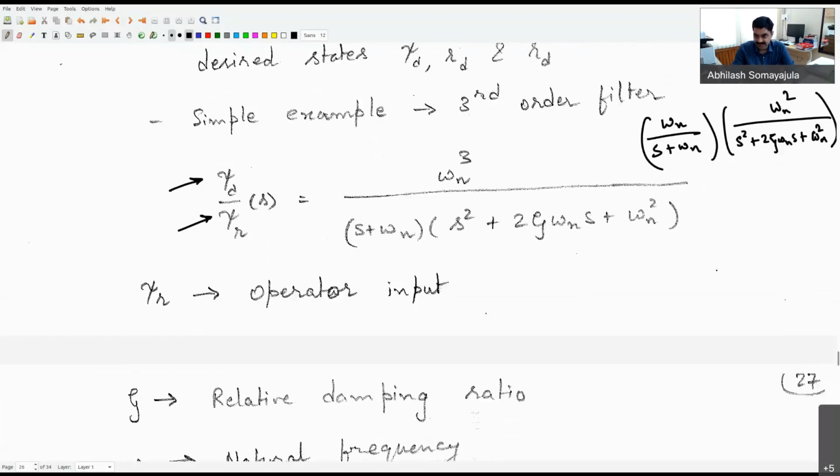The main idea here is that we get to choose our damping ratios and natural frequencies as we desire. Depending on them, the signal will be as slowly varying or as fast varying as our requirement demands. And depending on the craft that you're actually trying to apply this to, you may want to choose your omega n and zeta values accordingly.